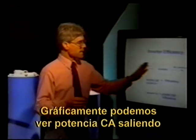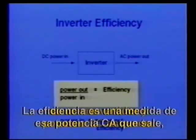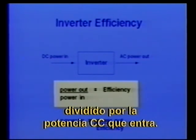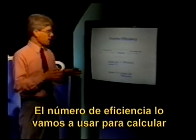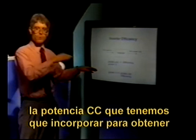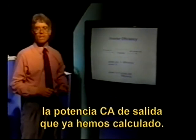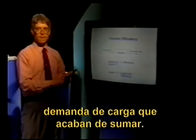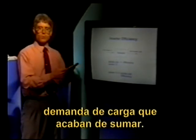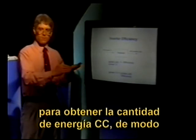Graphically, we can look at AC power coming out of an inverter and DC power going in. The efficiency is a measure of that AC power out divided by the DC power in. What we're going to use the efficiency number for is to calculate the DC power we have to put in in order to get the AC power out that we've already calculated. Remember, the AC power out is your load demand that you've just added up. What you don't know is the number of modules you need to give you the amount of DC energy so that it can be converted into AC.